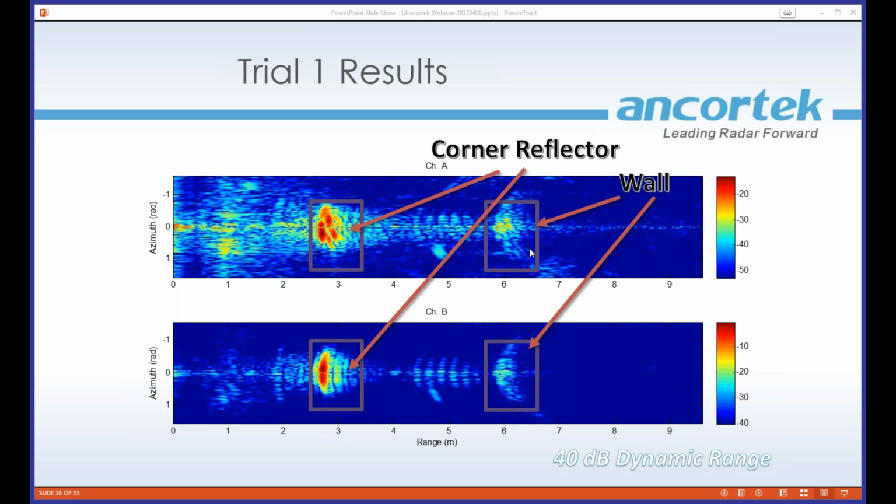So we used this open source software, RTKlib, and a separate base station, and then the Chorus base station over at the airport to give us really spot-on GPS results. So essentially, I knew where the collections were when I took them, not necessarily where each position or each step in the radar was. But yeah, you don't need it as long as you have a pretty well-defined knowledge about where the radar is and what you're looking at.